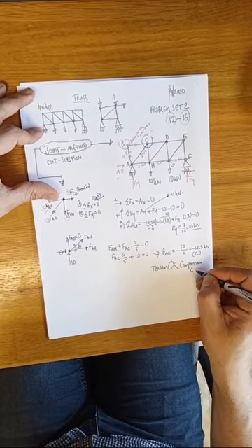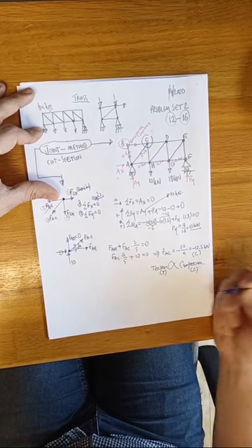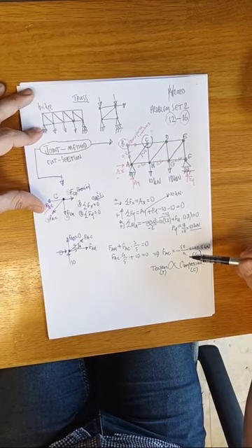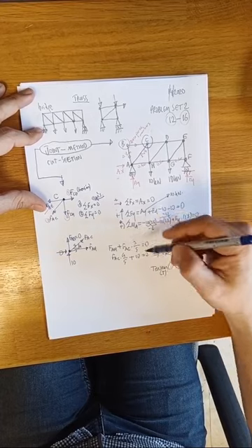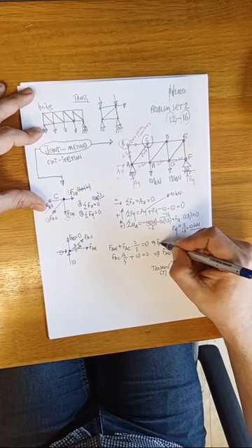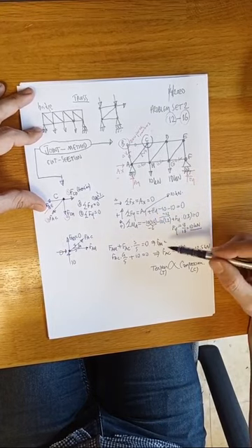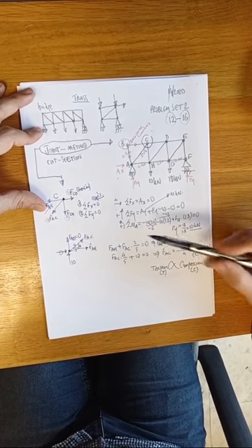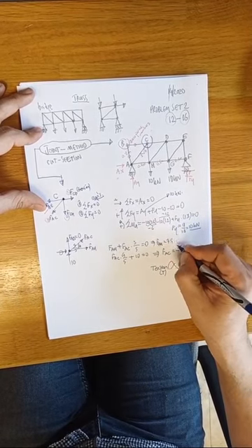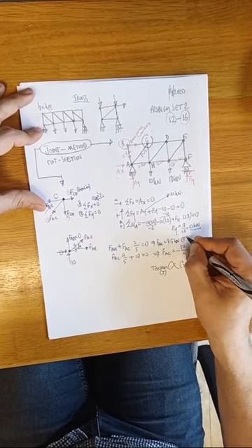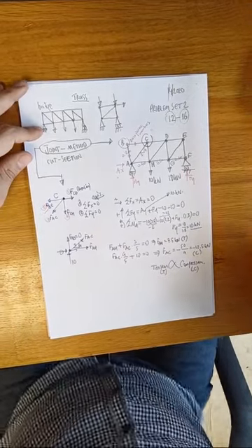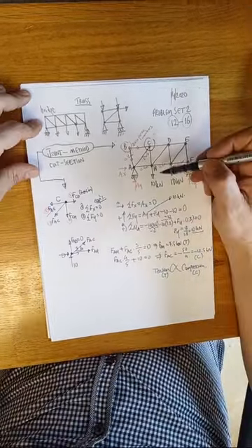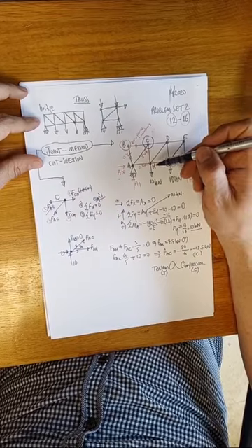Okay, we call it C, this is T. So from this, if you know FAC, insert FAC here to find FAH. So when you insert it, you will find 2.5 times 3 will give you 7.5 kilonewton, which is tension. Okay, by this way you can continue with the other joint.